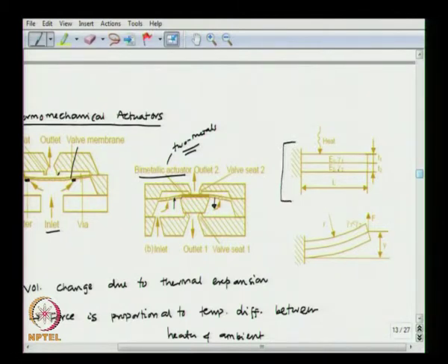So, this is the scenario we have. We would have 2 different metals bonded to each other. They could have different thickness, and when the heat is applied, because of the difference in the thermal expansion coefficient, in this case gamma 1 is less than gamma 2, the bimetal is going to deflect. So, there is going to be a maximum gap at the tip of the bimetal, and there will be an actuation force F, which can produce equivalent deflection.